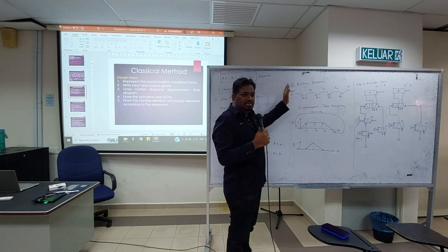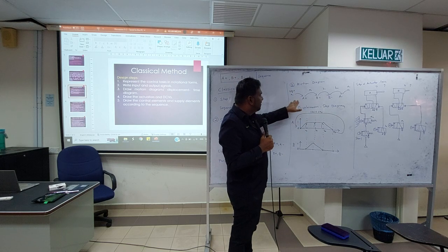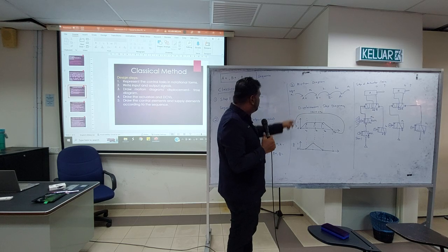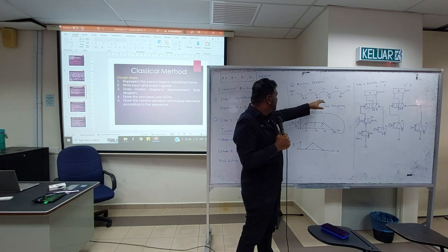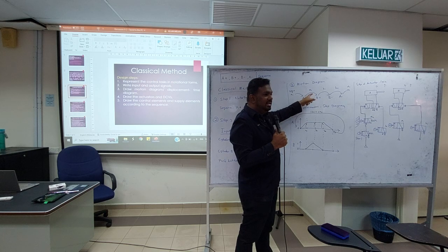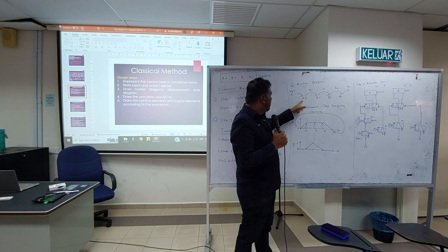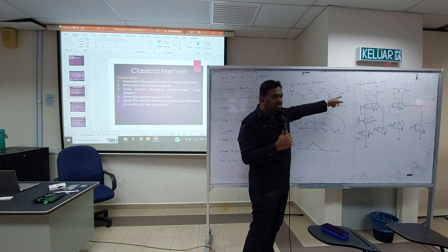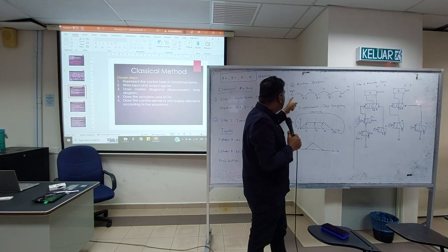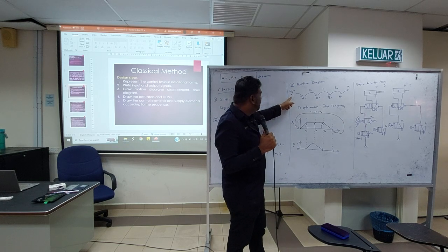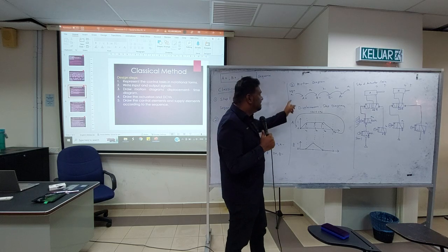Okay, tak perlu lukis dua-dua, so no need to draw both. So either one. So I prefer this because you already have all the information. So lukis dulu sequence. So A plus, B minus, A minus. Then when it extend, what will be the state of the input? Ataupun sensor. So A plus will activate A1. So A1 will activate B plus. So dia akan ikut sequence lah until the end. And what is the starting condition? So initially, so A0 must be on, and also you need to press the push button to start the sequence.